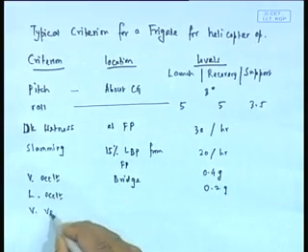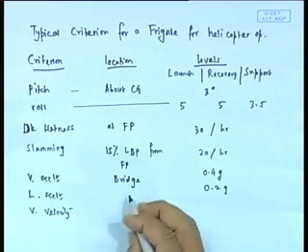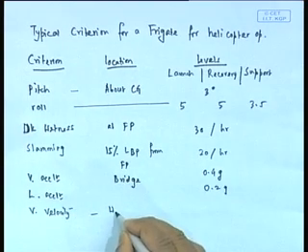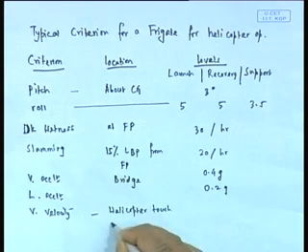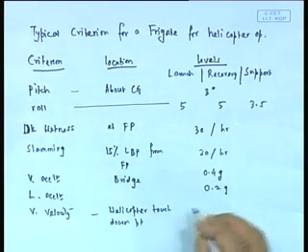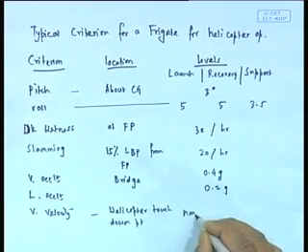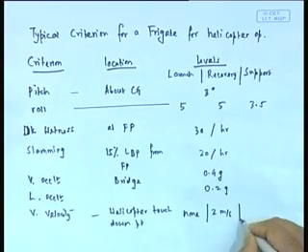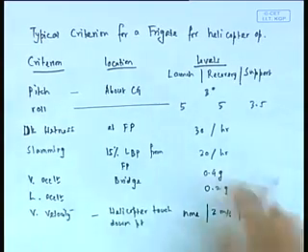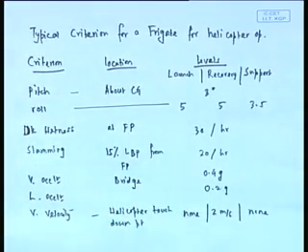Vertical velocity, where? At helicopter touchdown point, it says launch time is none. Recovery time is 2 meter per second and support time is none. See, what I am saying, this kind of table one has to make, or a designer has to, when you are designing it, the owner has to specify that for my ship I want this criteria. Okay.